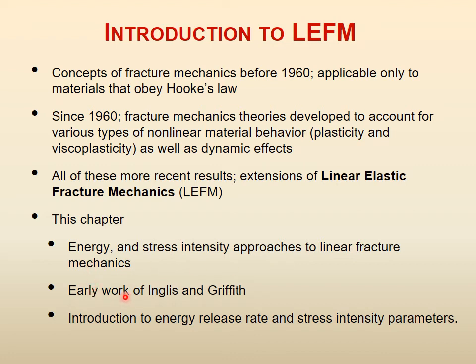We will see the early works of two major scientists in this area, Inglis and Griffith, and we will introduce to ourselves energy release rate and stress intensity parameters. So this is overall what we will cover in linear elastic fracture mechanics. Of course, the field is large and we are doing just a first basic introductory course. Otherwise, even in linear elastic fracture mechanics, we can go much higher.